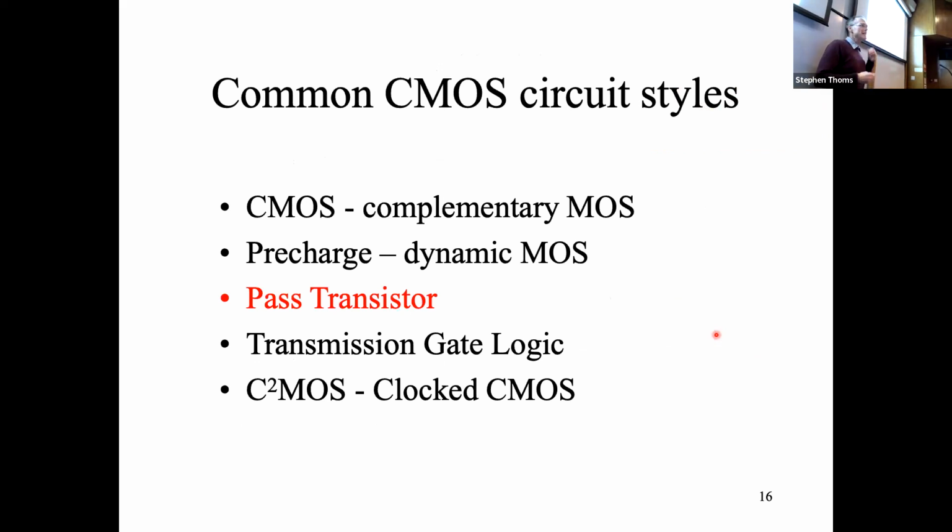Pre-charged logic, by the way, is still used. It's had its heyday, really, I suppose, if you look back about 20 years ago, when companies were trying to get the maximum out of microprocessors in terms of speed. Obviously, still trying to get speed, but the emphasis now is more on making lots and lots of cores. And pre-charge actually is quite tricky to use, so it gets used mainly in niche applications. The CMOS logic, which you looked at first, is generally the first go-to type of logic. But having said that, these other ones do exist, and we look at them because, as I say, in niche applications and certain types of gate, they are useful.